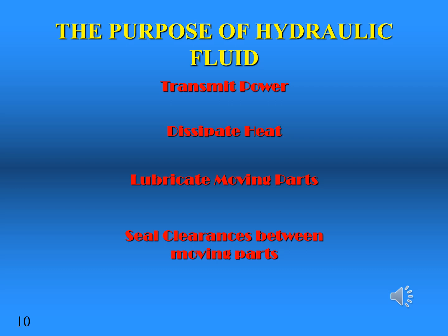To be an effective and reliable lubricant, hydraulic oil must possess properties similar to most other lubricants. These include foaming resistance and air release, thermal, oxidation, and hydrolytic stability, which is the ability of the lubricant and its additives to resist chemical decomposition in the presence of water, anti-wear performance, filterability, demulsibility, which is the ability to release water, rust and corrosion inhibition, and viscosity in respect of its influence on film thickness. When oil contacts a surface, it forms a strong molecular barrier.